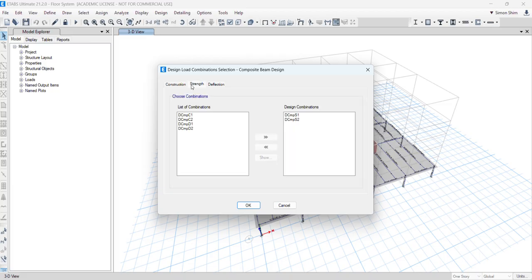After the concrete is fully cured, it develops the composite action, so the beam and slab are compositely glued together. Then the stiffness and strength are much higher, so we make use of the benefit of composite action for the permanent beam design.